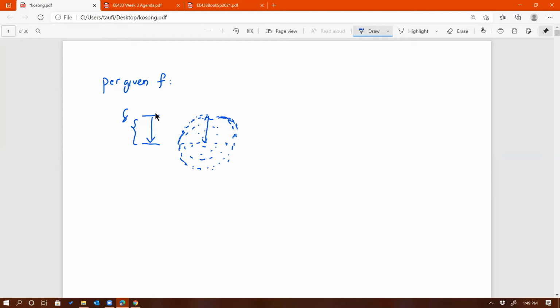So something like, let's see if I can draw that, something like this, maybe. So a smaller wire, basically, because the skin depth is about this much. That's the skin depth, and there's the radius of the wire. So if the skin depth all around the wire is that much, then you can see that the entire cross-sectional area of the wire will be used, for sure.